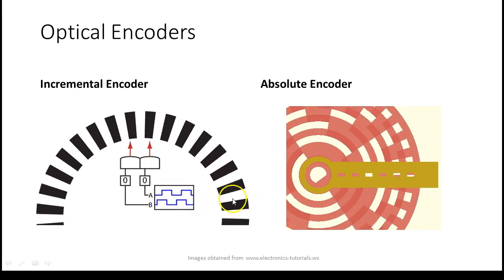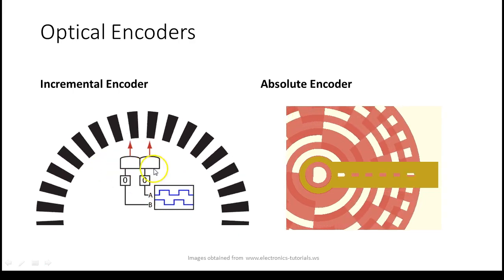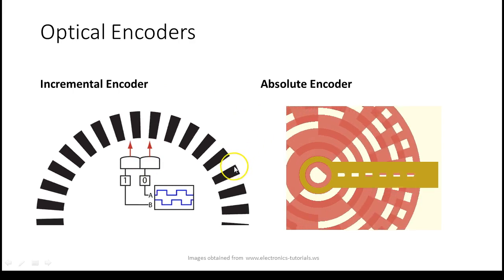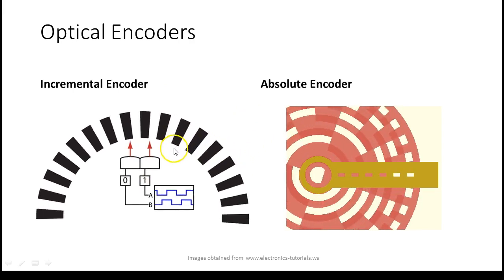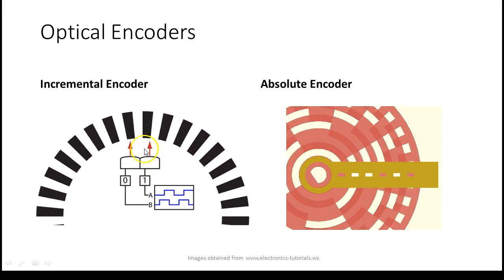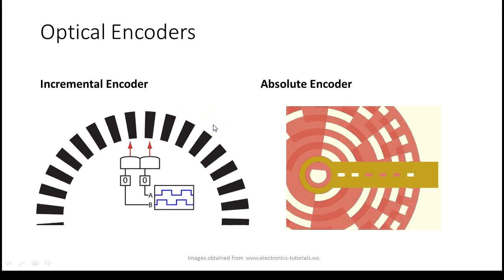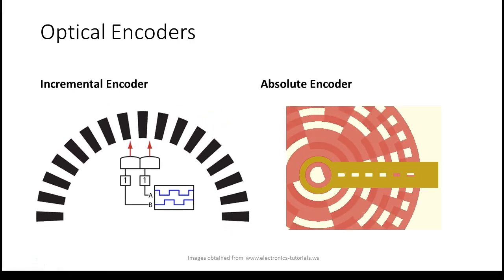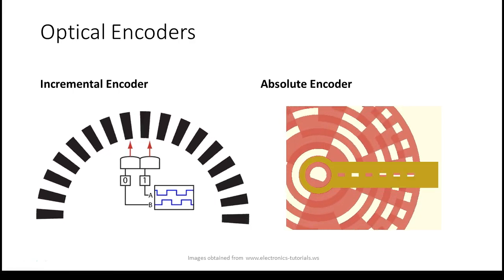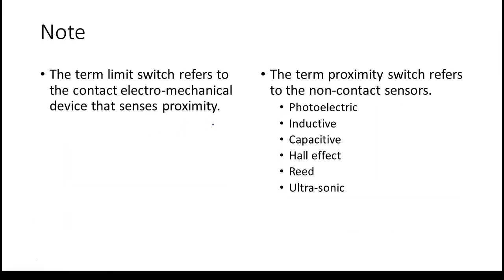So what does this tell us? Unfortunately, I can't reverse the animation, but if I reverse this up here, then what would happen? Either the sensors could be stationary and the encoder wheel could move, or the encoder could be stationary and the sensors could move. The most popular way in robotics is to move the wheel and keep the sensor stationary, because the sensors have to be powered up, right? But if you look at your print head, it's got all those flexible wires going up there anyway.